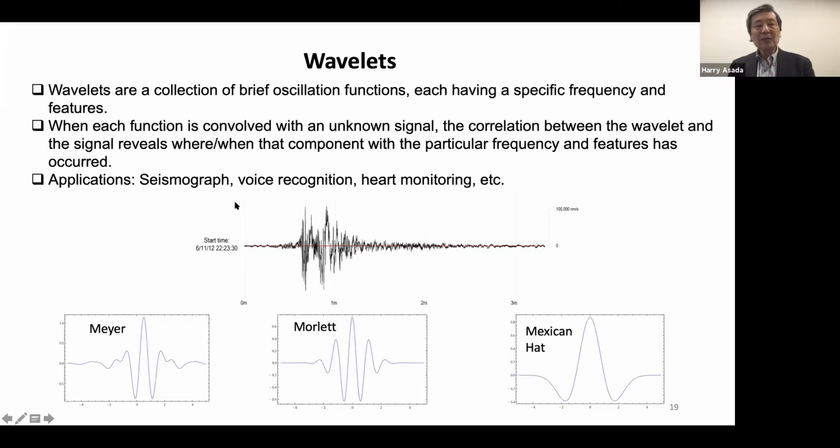Okay, so that's actually some kind of earthquake vibrations recorded like this. As I said, the earthquake does not happen all the time, so it is mostly quiet, and suddenly it's actually having some peak and then diluted, right? So if you just use the Fourier transform, you just average out such important features, and so you don't get any trait in that. But if you use the wavelet, this pattern, how much of them is involved in which location, you can find that information coming out of it.